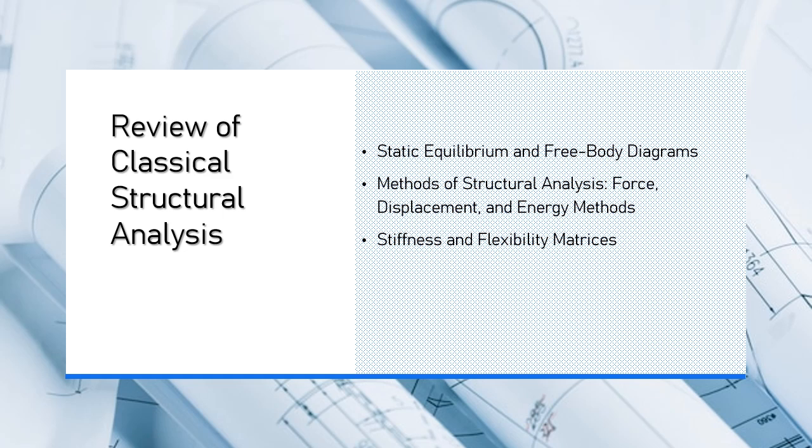2.4. Applications of static equilibrium in free body diagrams. Trusses. In truss analysis, they're used to calculate internal forces in individual members using methods like the method of joints or method of sections. The equilibrium equations help determine the forces in the members of a truss that are in static equilibrium. Frames and arches. For more complex structures like frames and arches, free body diagrams help decompose the structure into simpler parts, allowing engineers to solve for internal forces and moments.